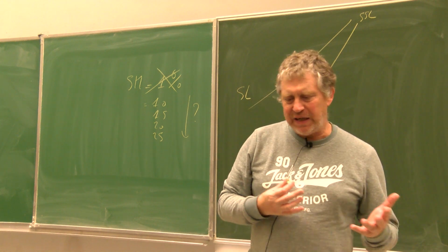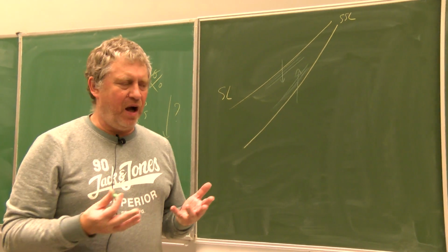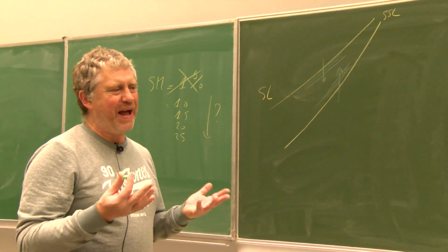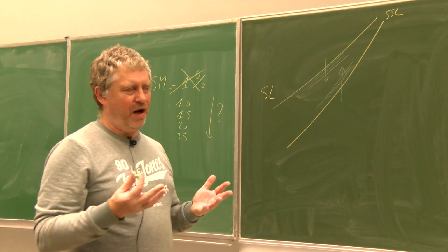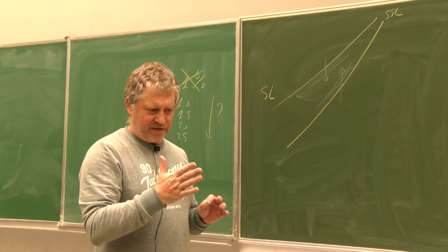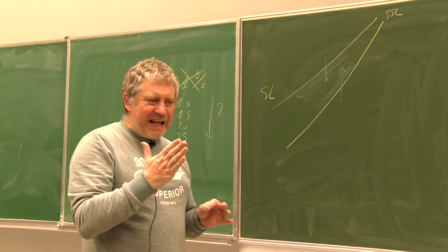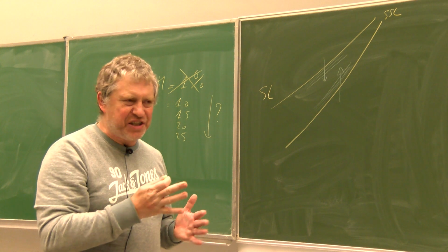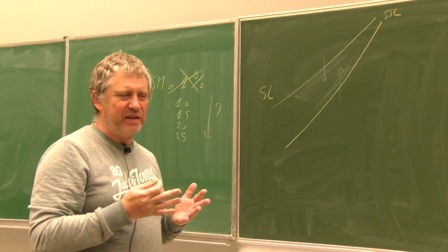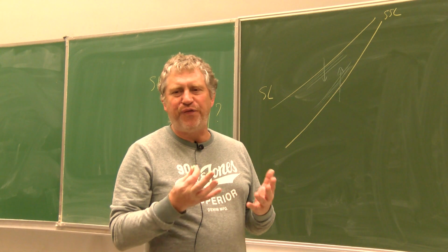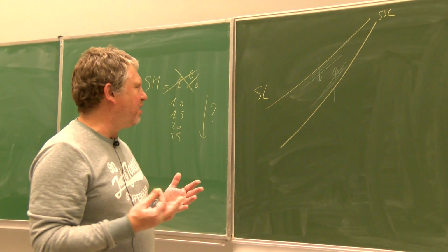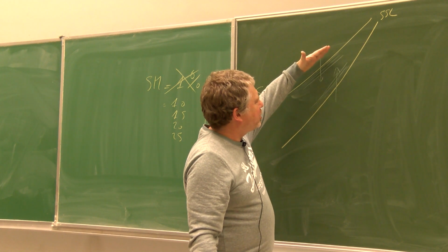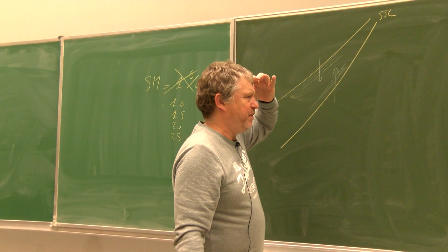We have seen one downstairs on the fan of the F100, the tolerances. So with time, the blades are moving. The blades are degraded. So the leading edge is not anymore at the place you wanted to have it. The leading edge has been deformed. So these are certainly very good reasons leading to the fact that the surge line will go down, will go down, will go down. Okay?